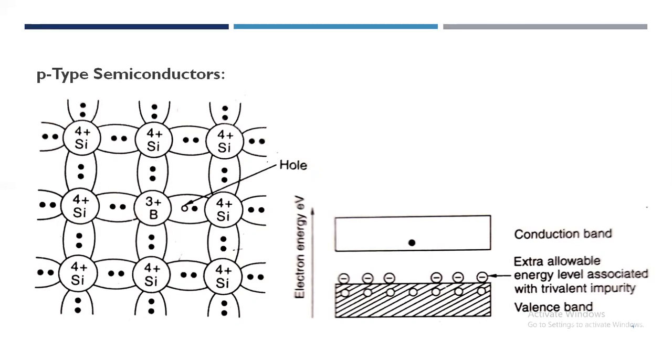In these P-type semiconductors, we are dealing with boron and silicon, and boron is from the third column of the periodic table. Third column means the outer orbit of boron has 3 electrons. As in the earlier pentavalent case, these impurity atoms from the third column enter the crystal structure and take places normally occupied by the silicon.